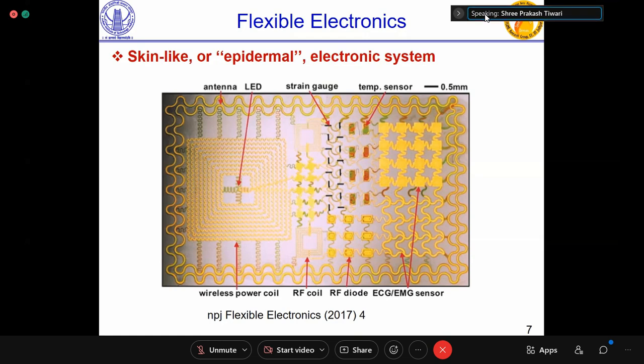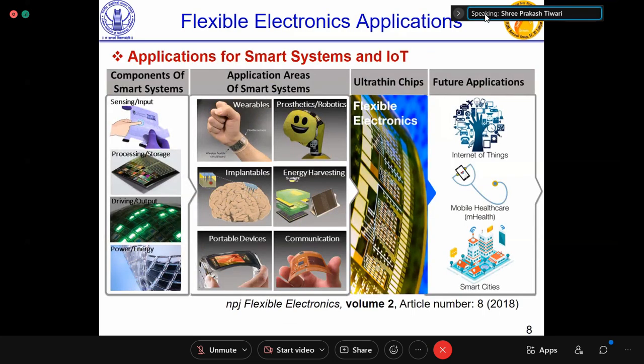But when you design these kind of systems, you cannot use just straight line metal interconnects for this system. So there also, when you say something is stretchable, it means you have to give it a flexibility so that even if you stretch, the actual length of the connection increases, but it still doesn't break. So if you have a pure straight line, if you stretch it, the metal will break. But if you have some helical or some kind of spiral structure, probably it can still be stretchable. So these kind of thoughts are always embedded in any skin-like electronics, which is thought of ever.